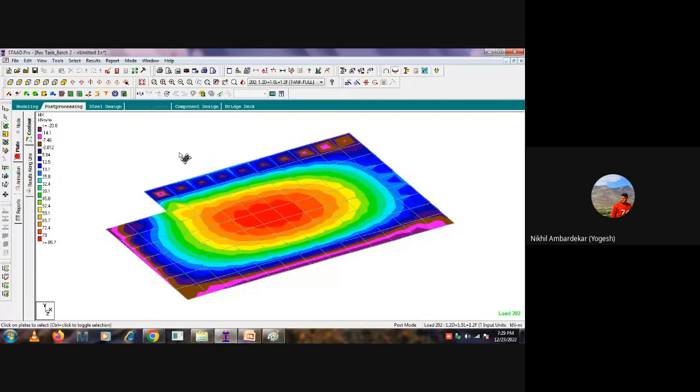So now again, basic things. This is our top slab. So does anyone want to understand why this is like this? This is the roof slab. That's why I just deleted some plates here to consider as an opening. Okay, so we need some space to enter the tank. That's why I simply deleted 3 into 6 plates here, so we can have some opening through the slab. Just assume a random size and I deleted 6 plates.